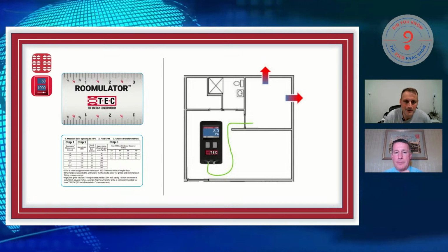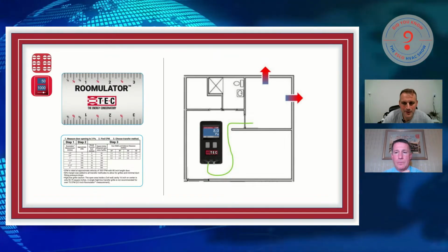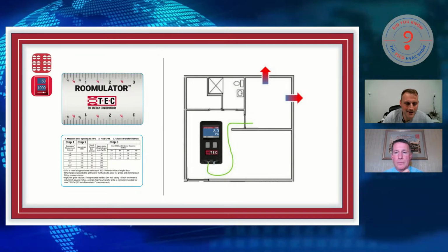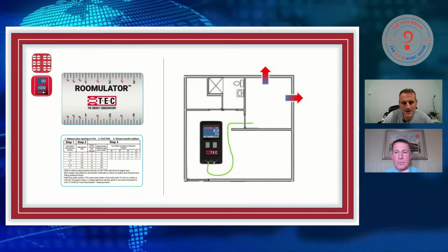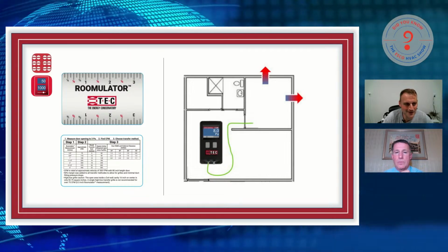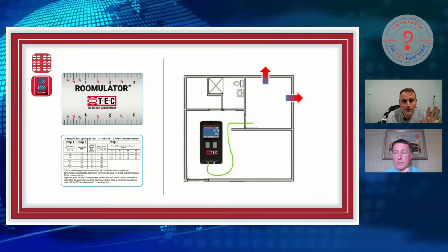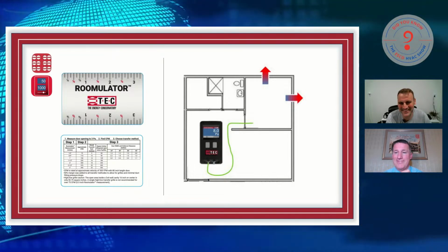So when you figure out what size drop you're going to do, you don't have to worry about, I got these grills, does it matter? There's going to be enough fluff built into the measurements to absorb it. So don't worry about it. Just trust the card and it'll get you there. And if you come in under 3 and you're at 2 pascals, so be it. That's even better, right?